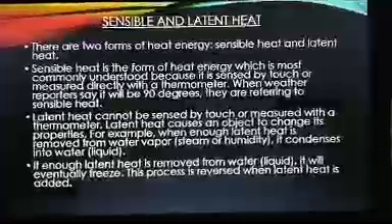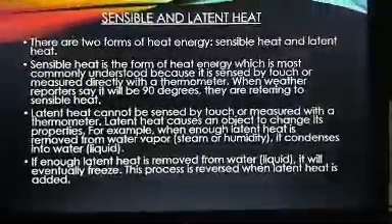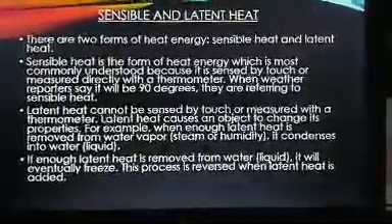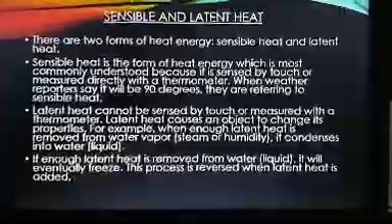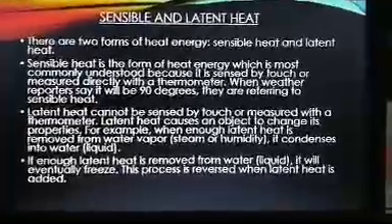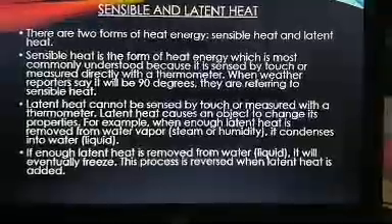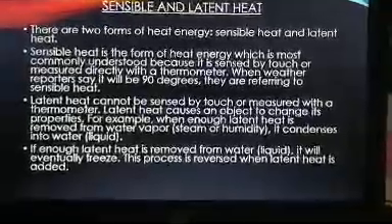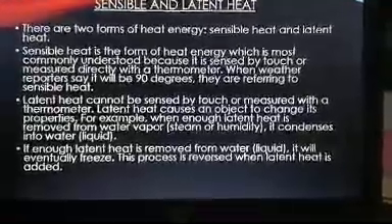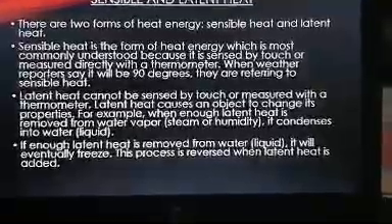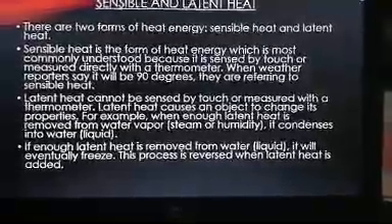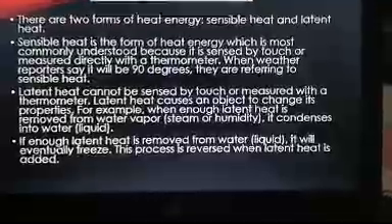Sensible and latent heat. There are two forms of heat energy, sensible heat and latent heat. Sensible heat is the form of heat energy which is most commonly understood because it is sensed by touch or measured directly with a thermometer. When weather reporters say it will be 90 degrees, they are referring to sensible heat.